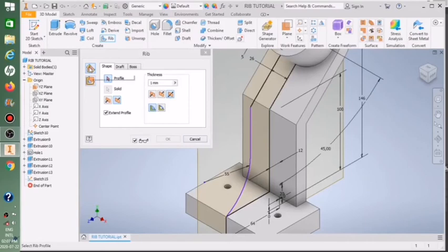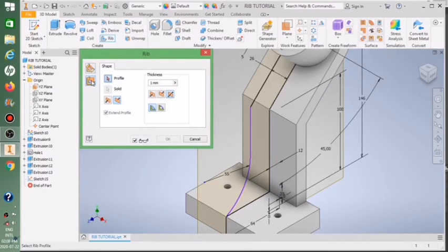And then, as you can see, it's normal to sketch plane. I will be as slow as possible from this one. Normal to sketch plane, and then there's parallel to sketch plane. We want that parallel to, and then there's finite, and then there's to next. There's extend profile. So we won't use normal at this point. We will use parallel to sketch. We click parallel to sketch, and then